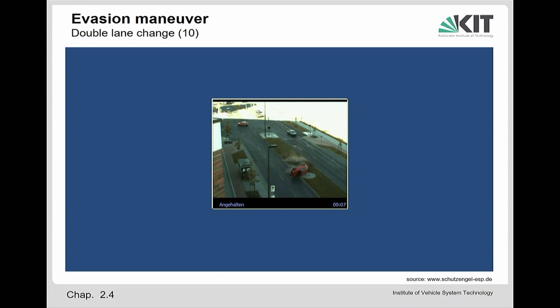So this is a typical situation which happened in the past pretty often. If a very, very abrupt steering maneuver was necessary at high speeds, I'm pretty sure that this guy here has also activated the brake. And activating the brake means also to weaken the opportunity to transmit side forces. So it was a very critical situation, and you see the car gets completely unstable.